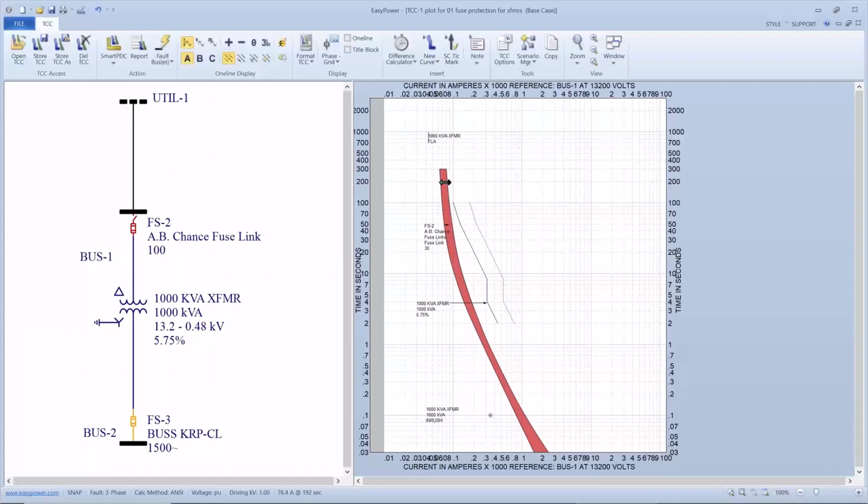So if I hover over the fuse, you can see it's a size 30, that gives me protection for this 43 amp. So it's nowhere near the 300%, but it's full protection. Now, I haven't talked to the manufacturer, and I suspect that the manufacturer would tell me the size of the fuse that I would want to order.